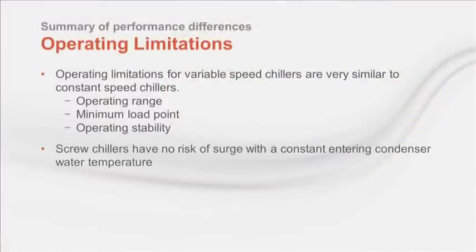As discussed, the biggest performance difference between centrifugal and positive displacement compressor technologies is that in applications with constant, elevated condenser water temperatures, a screw chiller can unload with no chance of compressor surge. That doesn't mean a screw compressor can operate with any condensing conditions.